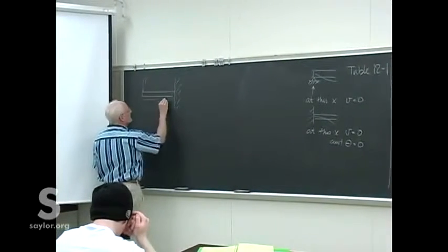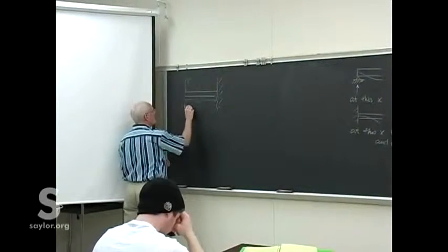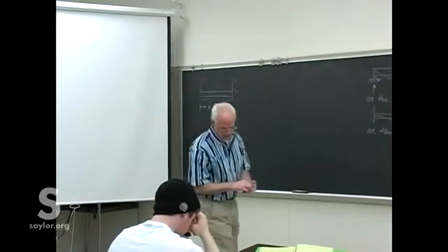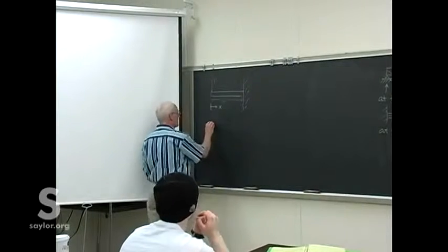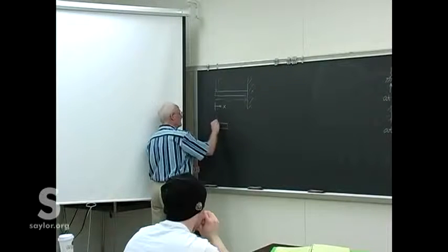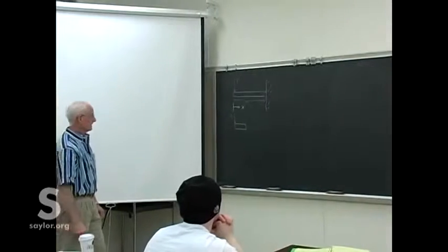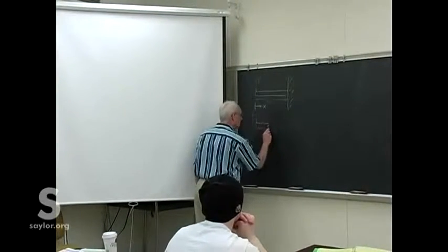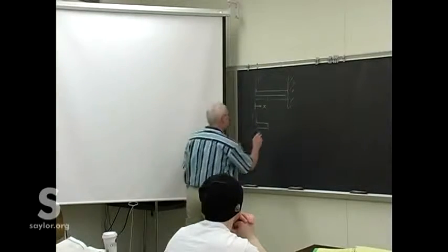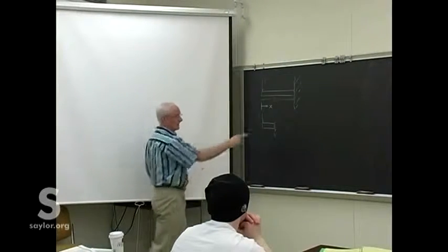So beam of length L, and we'll measure x from that free end where the load is. All right, so just to get going here, we'll do a quick free body diagram of a piece of the beam. Let me do it the way the book does it. Start with everything drawn in the positive direction, and then if it gets a negative sign, we'll just keep it there.